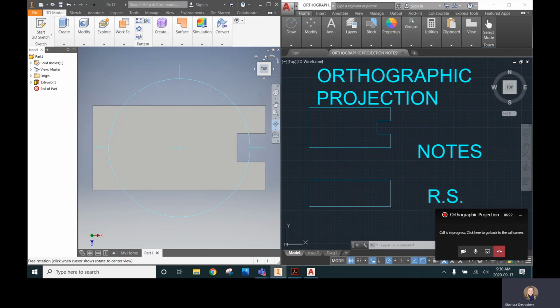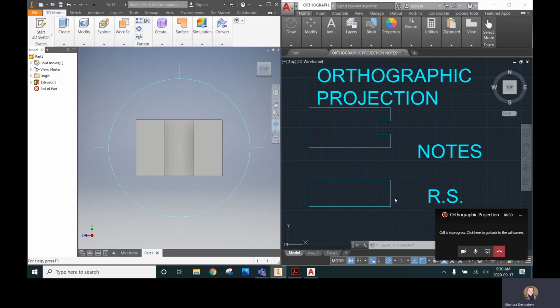So if we go back to our front view, we'll rotate to what the right side looks like. Okay, it's a rectangle with 3 parts. So that's fairly simple. We can draw that. I'll get rid of my right side here, go back into the line function, take this corner and draw over here, click, and then hover on here and draw, click. Again, this is saving me time. That's the whole point: we're lazy. We want to be more efficient. We don't want to waste time drawing things that we don't have to.